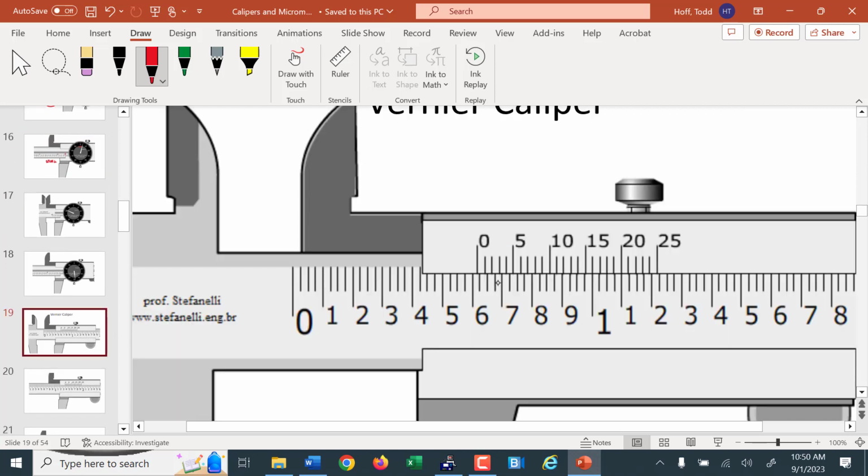This is the vernier, by the way. I don't think you guys need to know the vernier. Anybody curious to see how it works? Not really. So you read the main scale where the 0 is. So this would be 0.6 inches. And then you do have quarter marks there. We're not past any of those. So it's just 0.600.